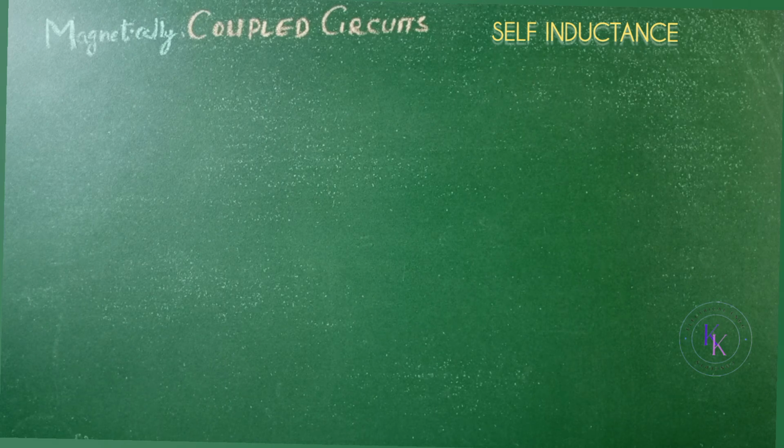A wire of finite length, when twisted into a coil, becomes the simplest inductor. As soon as current flows through the coil or the inductor, an electromagnetic field is formed. However, when there is any change in the flow or direction of the current, the magnitude of the electromagnetic field changes. This change of field induces a voltage V across the coil.